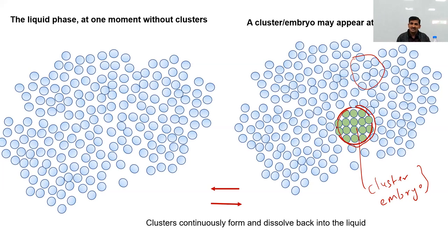That tells us that the structure of a liquid is not a static, fixed kind of structure. There are atoms which are wobbling around, vibrating, with quite a bit of thermal energy. By pure statistical chance, some such atoms can come together in a configuration that happens to resemble that of a crystal. Whether or not these clusters or embryos grow into a crystal is a different story.